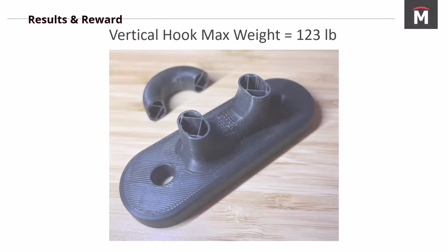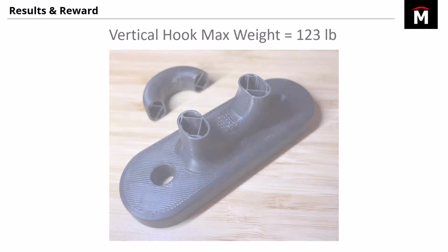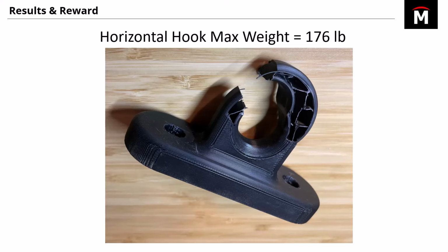Starting with the vertical hook, this one is probably the only one that broke about where I expected it to, and that is the thinnest spot in the hook itself. And it just broke right between the layers there. And so that didn't surprise me, but it did hold a lot more weight than I thought it would. I was thinking maybe this thing would be 60 to 70 pounds, but it made it all the way up to 123 pounds.